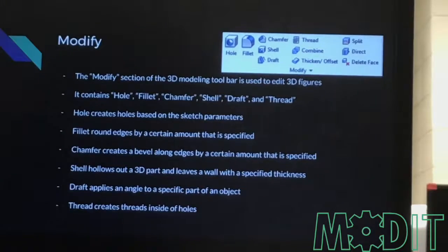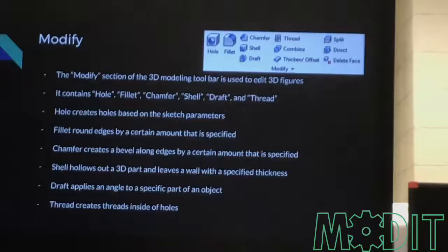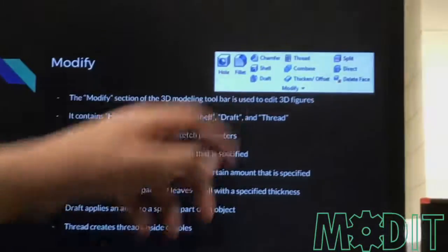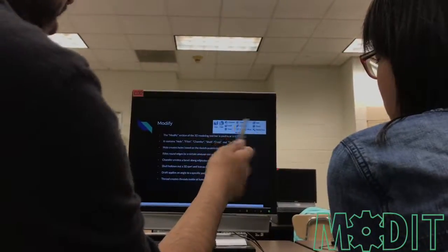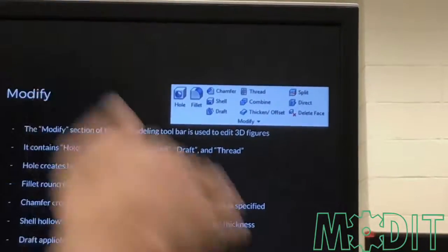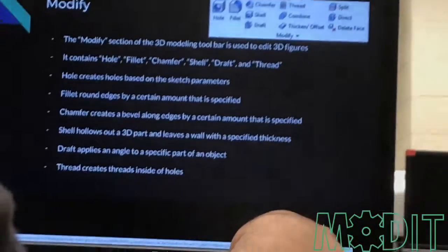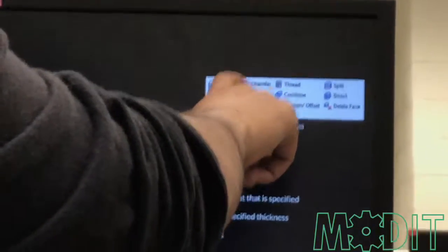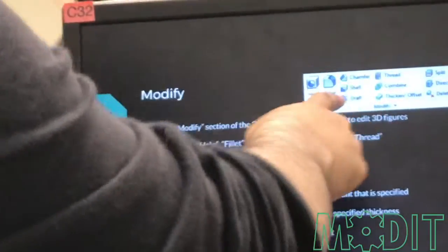So it's bevel, basically? No, bevel is chamfer. A chamfer is basically like that, but you do it at an angle. Most bevels are chamfered, at an angle. So that's what chamfer is. It's basically the same thing as fillet. You take the edge or the corner, but it goes on an angle, straight down. Fillet surrounds it. So chamfer will leave you with two edges, one on the bottom and one on the top. But fillet will leave you with no edge.